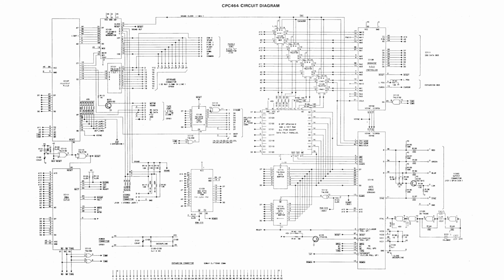Since we have a whole byte, that would in theory give us 256 different ports that we could address. However, Amstrad decided to take the top 5 bits and use one of each of those bits for each major I/O system: gate array, CRTC, ROM selection, printer, and PPI. That was done that way so that each chip could have just one line directly connected to it, and the logic to talk to that chip would be trivial.